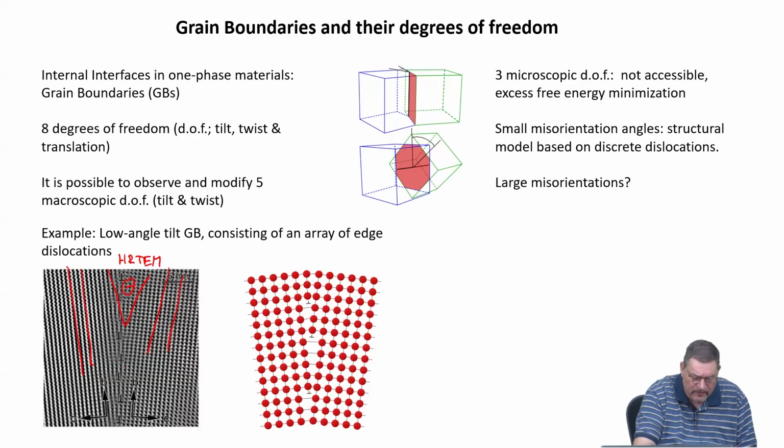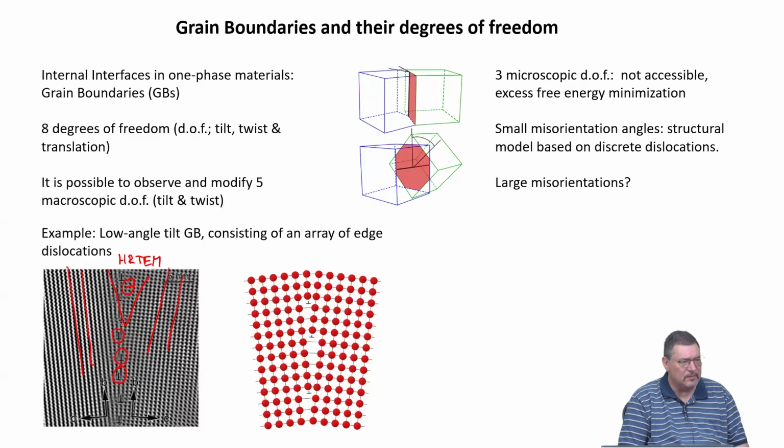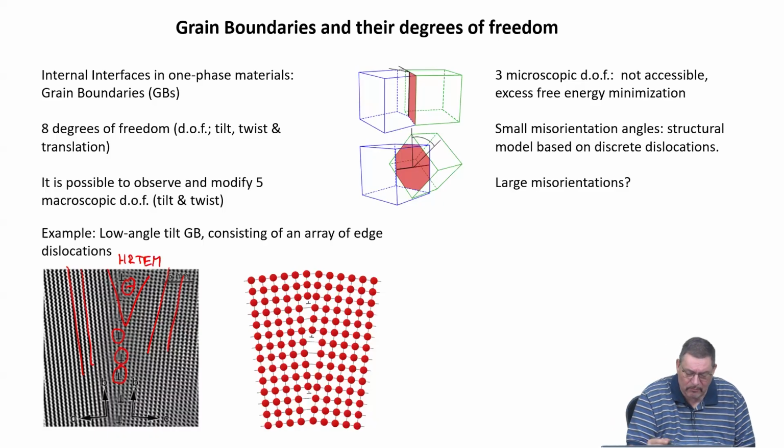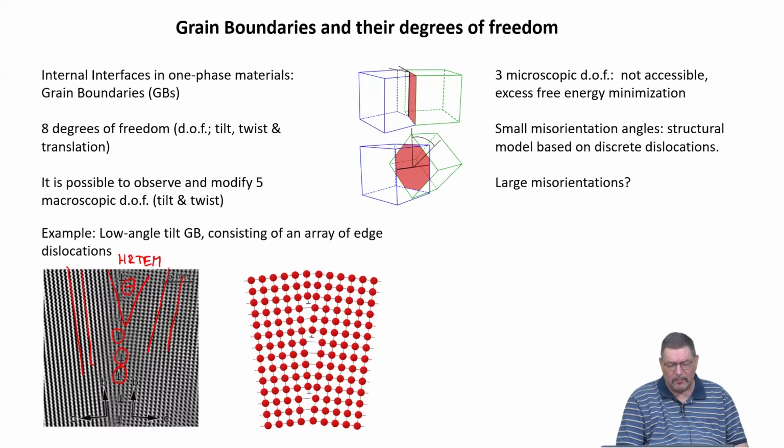You also see these funny symbols. They are the dislocations which have aligned themselves, because that minimizes the total energy stored in their strain field. This is why if you have many dislocations, you get cell formation, low angle grain boundary formation. And the nice picture replacing atom columns by balls in red is given here.